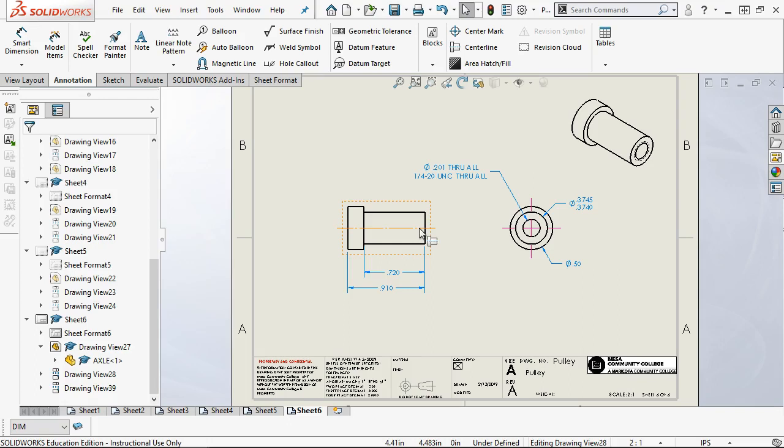Does it become a specialty item? What I don't want to get is one of them where it has to be 9/32, or it has to be 5/16. The further away we move from a nominal size, our 1/4 inch fractionals, the more expensive it's going to be. And at the end of the day, that's what we're trying for, is cost.